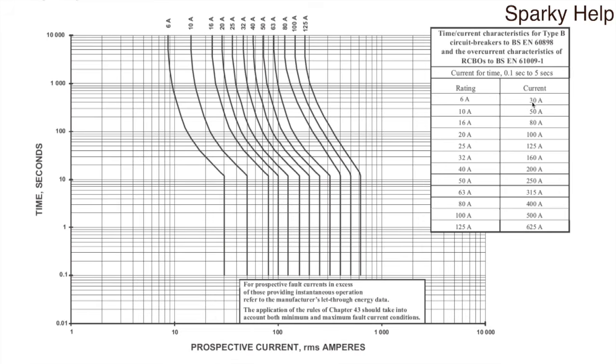However, interesting point to note, if you go 29 amps, so 1 amp under the threshold, if we look down here, so 29 amps, you can't get accurate, but you know it's just below that line somewhere, so it puts it there. And if we look across, that is over 10 seconds to disconnect.